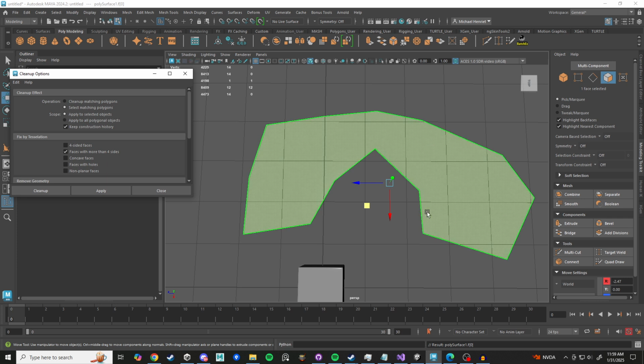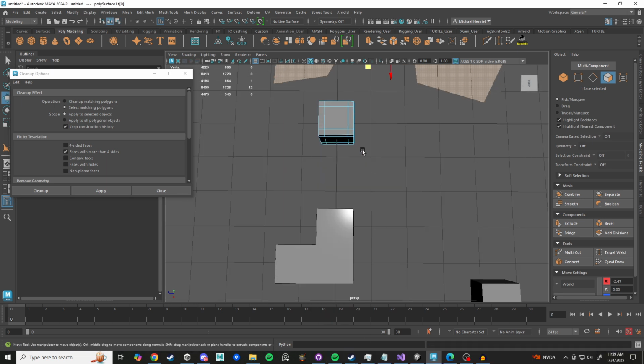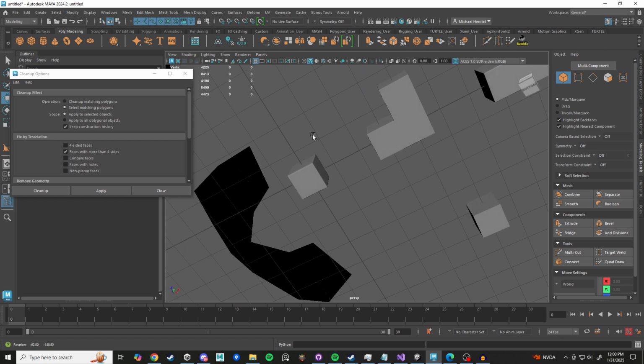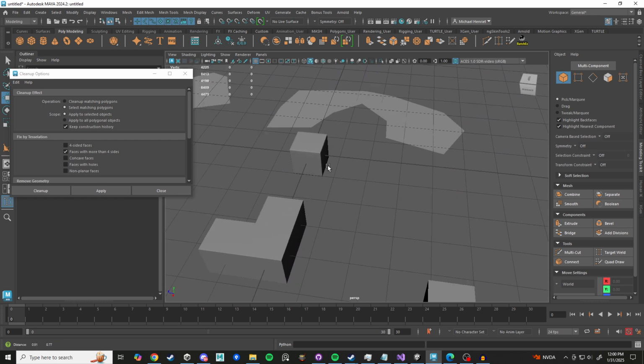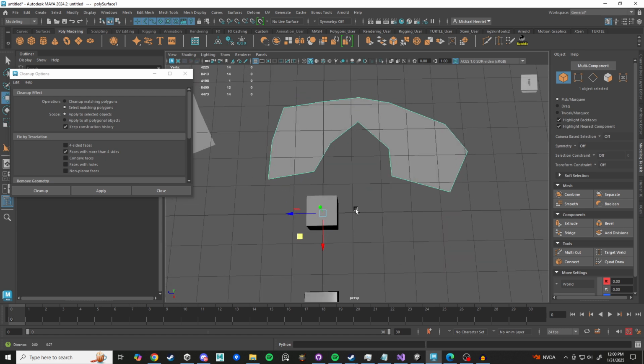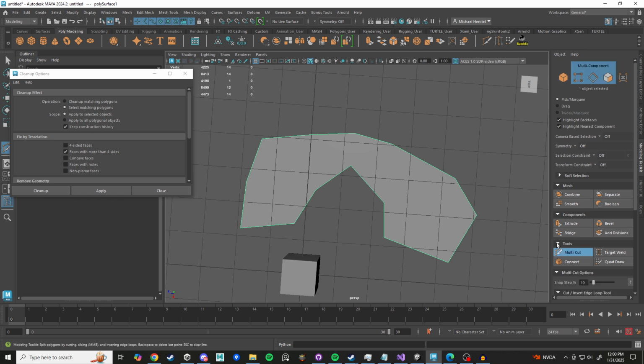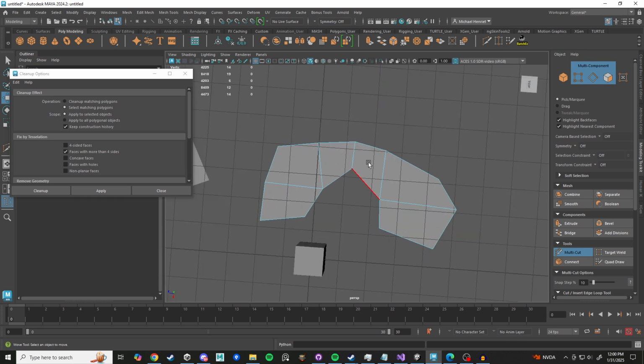We already knew it was an n-gon, but sometimes the n-gons are very sneaky, you know, like maybe we have one on here that we didn't realize. Let's see. Nope. See how it deselected everything? So we have fixed that one properly, okay? But when this happens right here, boom, whip out that multi-cut tool and just start fixing some of these quads. These are just quads waiting to happen, you know? There we go. So then let's run our mesh cleanup again.